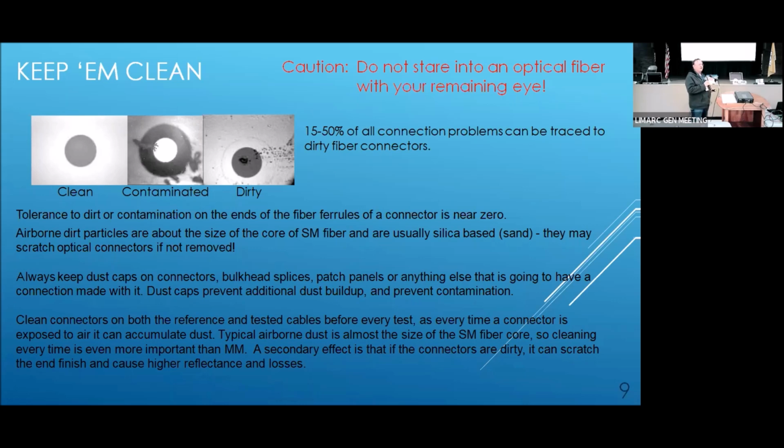To splice a fiber, they have specialized equipment that does it. It actually melts the fibers and puts them together, and you have an alignment tool that lines them up. You'll frequently see these things out on the street. Typically, it's done in the truck. They pull the fiber out of the manhole, and it goes into the truck. When they get it spliced and working properly, they then put some sort of tape around the fiber to protect it. And it goes back into the manhole, and then they move on.